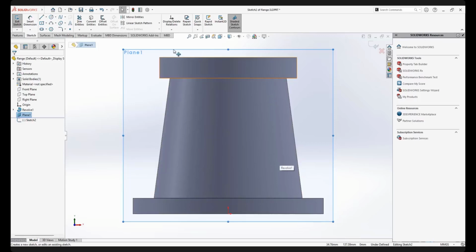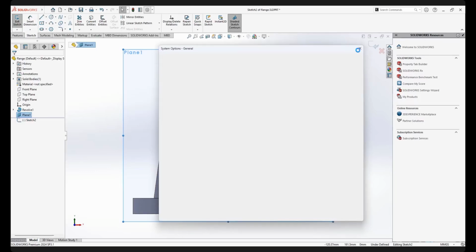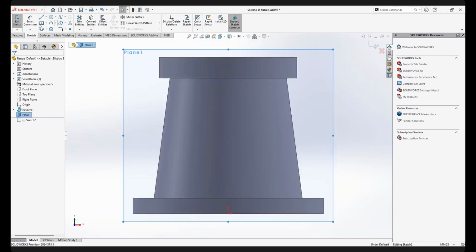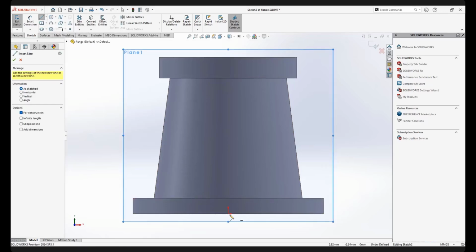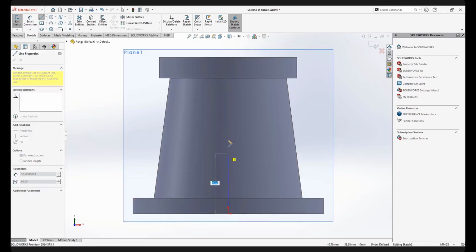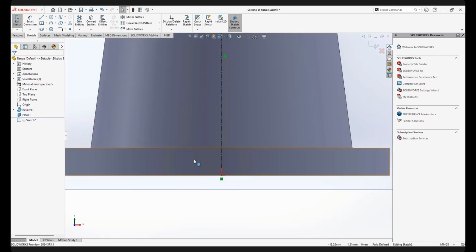Okay, now what I will do, because I need to draw the arm, I'm not in sketch mode. On this plane I've just created, I will draw a center line first, better to draw the center line first as a guideline. Since this is the middle, up until you can point it here. So this center line. I will draw my rectangle, snapping in the middle here.